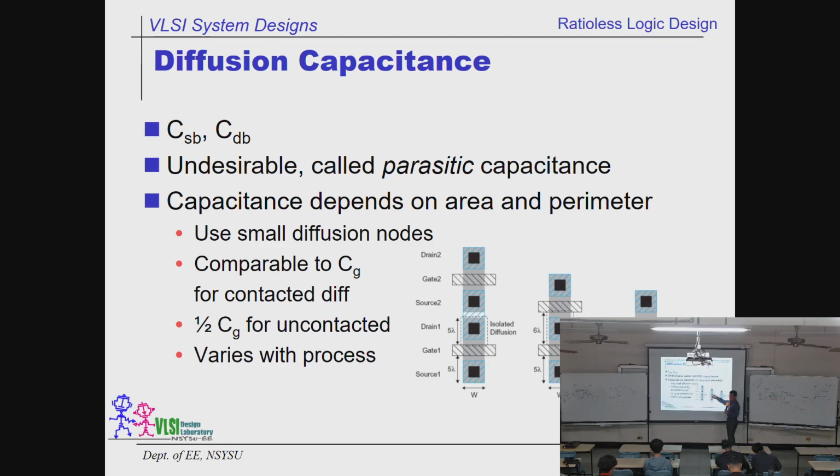So the best design is that we don't need it anymore. We just merge those two diffusions together, so we don't need anything like this. All we need is to follow the design rule. I use a big one. That's it. Then you don't have to pay the price of extra holes, extra metal, and extra space limitation between two devices.